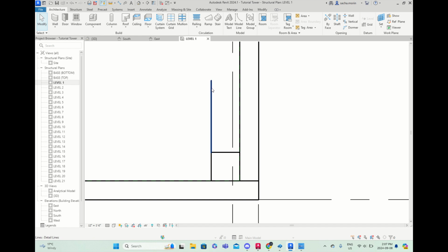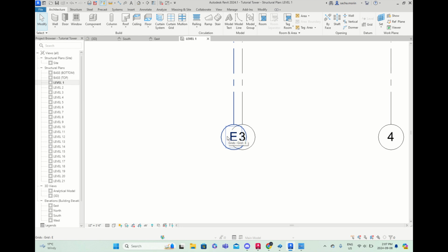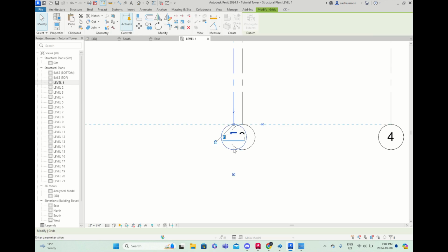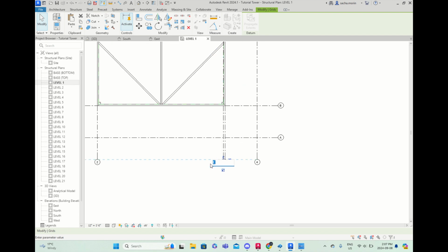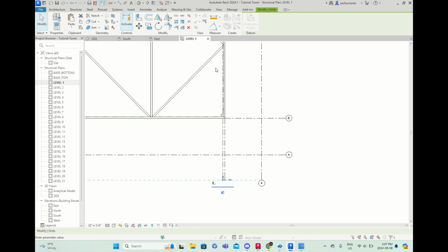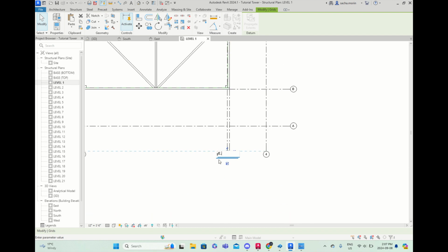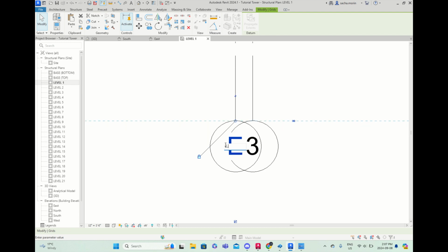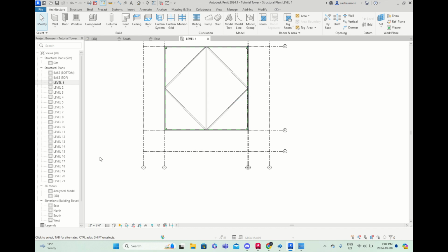Let's delete these design lines, since they're not very useful, and we can rename this grid line to something that will be useful for when we want to call it out when we're on our east side view. We'll call it E for east side view, and then E for exterior bracing, since it is on the exterior of our column. So capital E for east and short form E for exterior. Let's click enter, and that should do the trick.